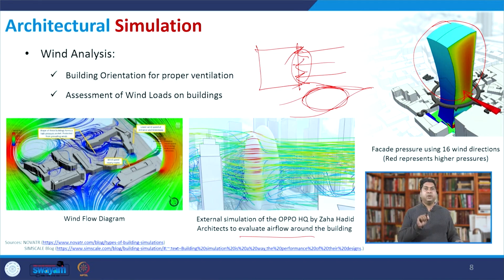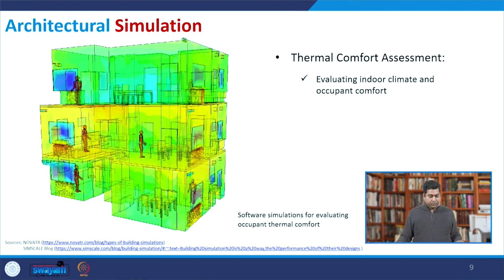Now accordingly you can change the parameters, you can change what kind of structural system you are going to adopt, whether you go for bracing, whether you go for some kind of outrigger structure, or an interior structure, exterior structure, or a combination, whether you go for a core, single core or split core. So those kinds of structural systems can be determined based on this analysis.